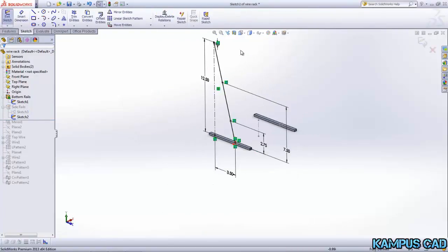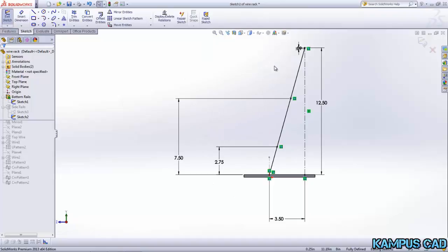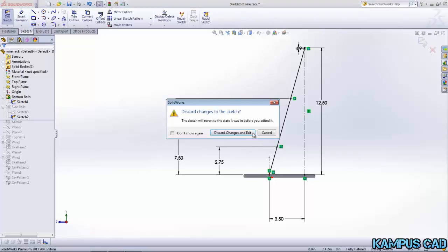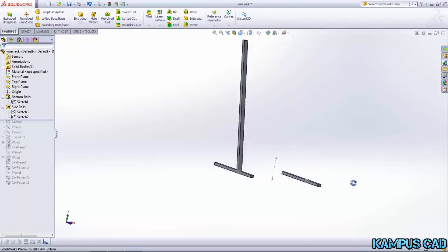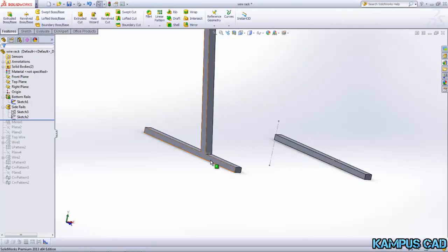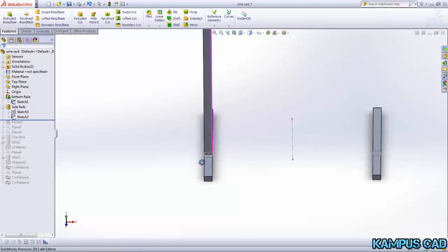So what I did was, I didn't want to calculate the angle that third basket is to the first one. I know where in space the center point of the first one is, and then the center point for the second one. So I just drew a line between those points. I drew construction geometry here, but you could just use 2 points and draw a line between them instead of trying to calculate out an angle. And I drew that sweep on the side of the rail here. And then my cross section, I just drew it tangent to that.